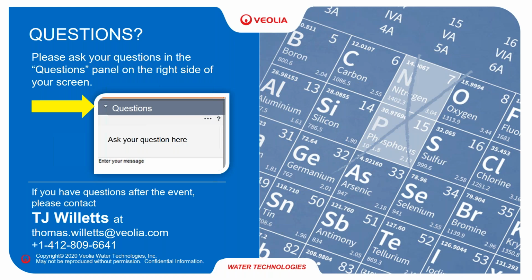If there are other streams that dilute the salt concentration so it's not as bacteriostatic, we can go biological. Otherwise, I would recommend going physical chemical, and high saline wastewater for active flow and disc filter are very well studied. A lot of our aquaculture applications use active flow and disc filters for nutrients removal from saline wastewater.